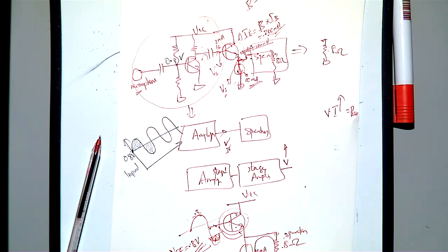During the negative cycle, this voltage becomes, say, minus 0.8 volt, and then your VB is minus 0.8 minus 0, so it will become negative. But during the negative cycle, this transistor will be on, and then through this RL, the current will come from the ground, and the emitter current will come, and then the collector will go through this point. You know what I meant? And then this transistor will be on, so that when you check your signal, you will actually get amplification like this.